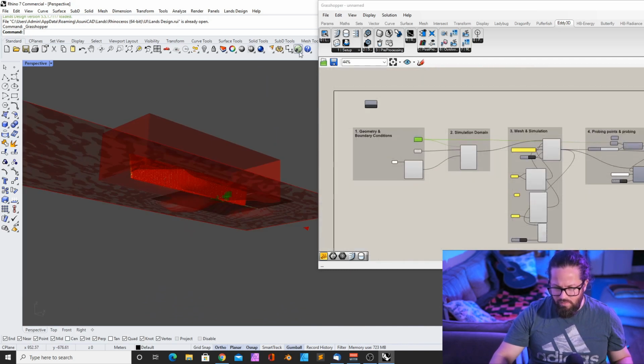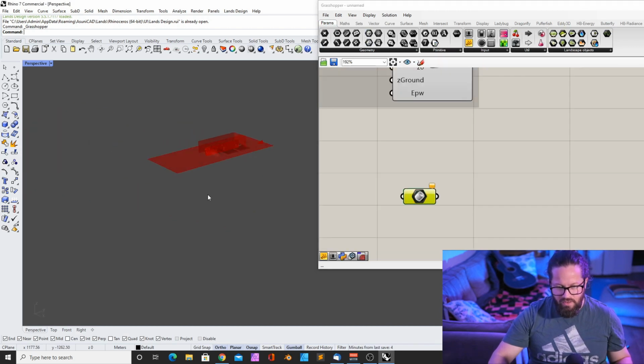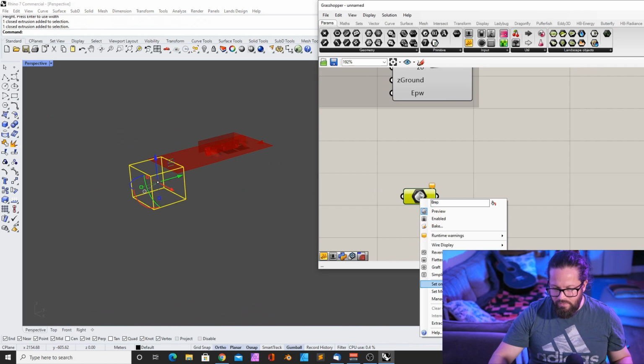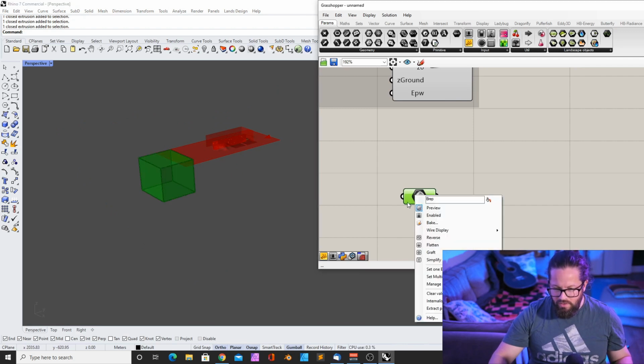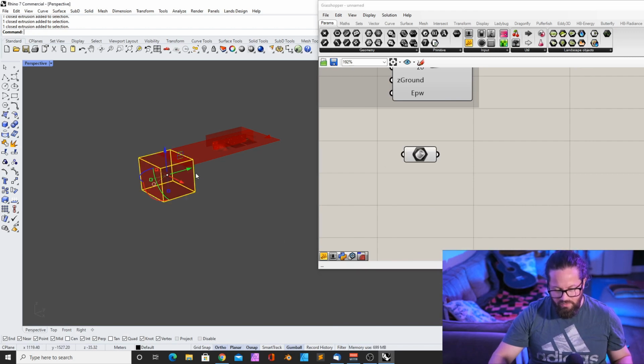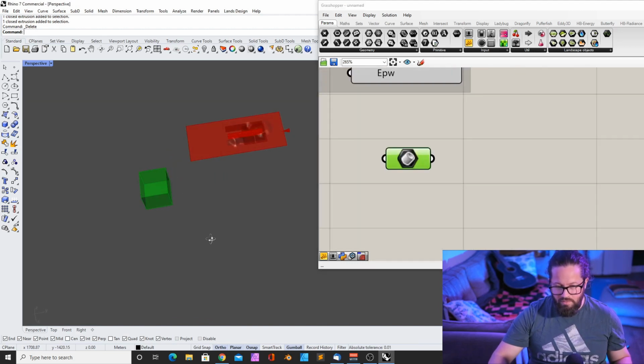How does it work? Well, for example, you have any container with geometry. I have this container, there's nothing in there, but if I want to put something in, I link this object here, then now this object lives in Grasshopper, but it also lives in Rhino. Now I can go here, right click, and then say internalize data. And now this geometry only lives in Grasshopper. And when you send and save a script like this, then you basically can send an object with your Grasshopper definition.